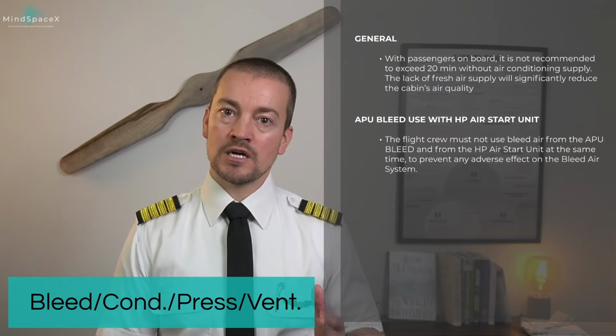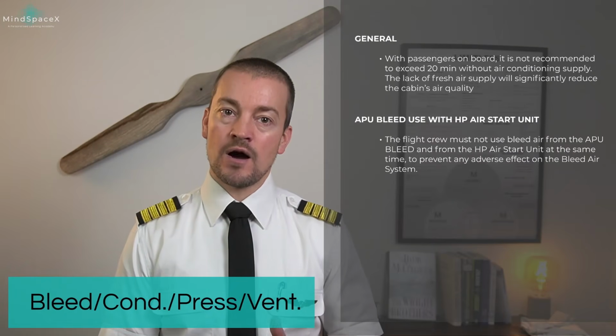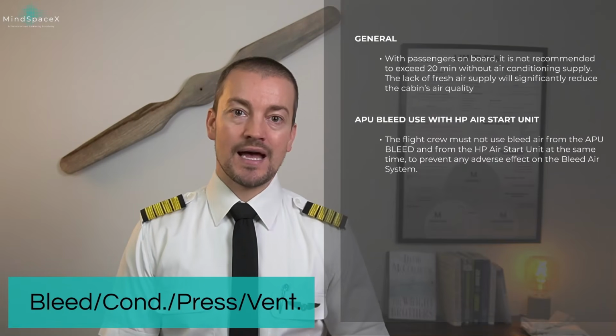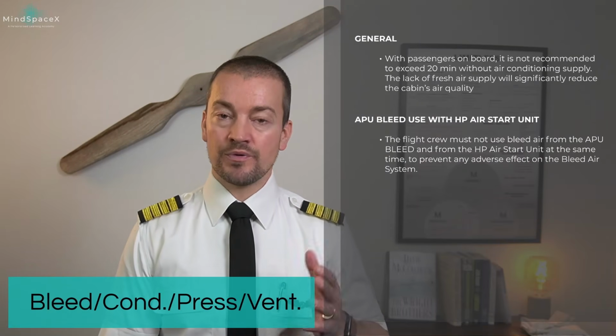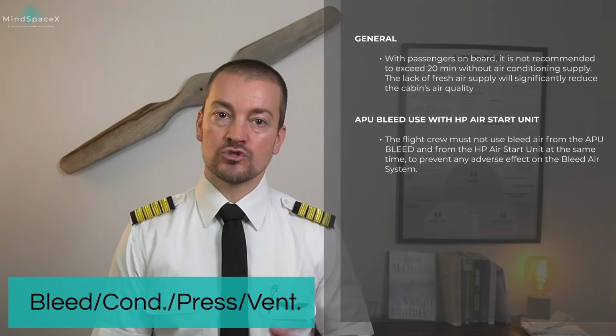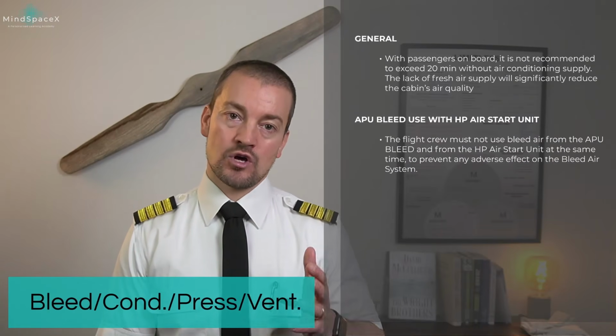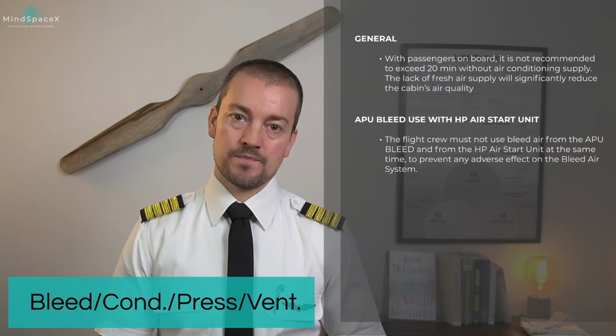The flight crew must not use bleed air from the APU and from a ground high pressure start unit at the same time. This is to prevent adverse effects to the bleed air system, mainly the bleed air valves. This will cause damage to the valves.